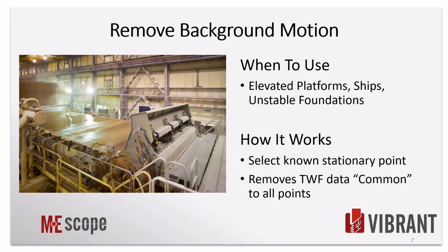And what we do is remove that time waveform data that's common to all the points in the video. It'll take that data associated with a known stationary point and remove it from the actual structure that we want to analyze, so that we know we're only getting the structure-borne noise directly related to the structure, not the peripheral vibration, if you will.